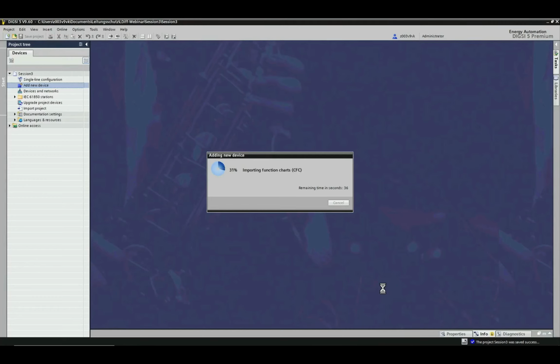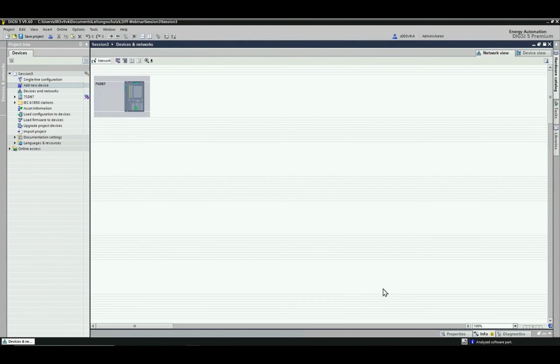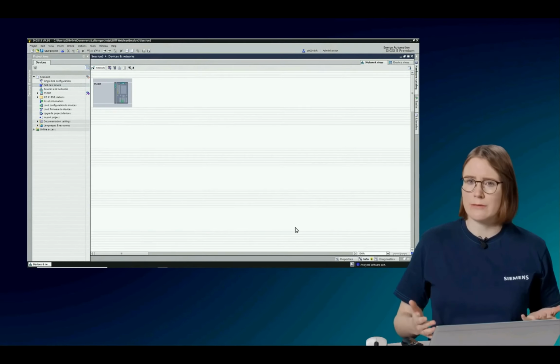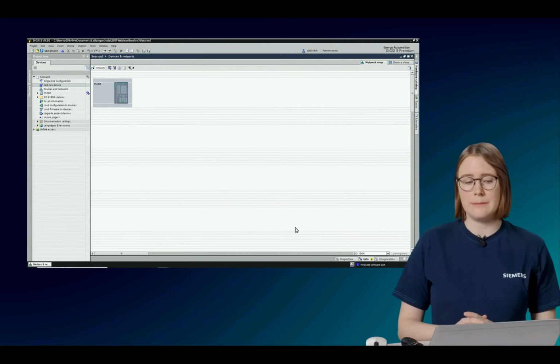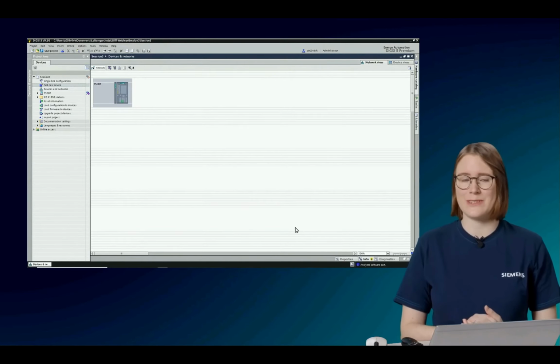So what I like doing at the very beginning of creating a project is to set the correct language and to set the correct setting mode. So do I want to do the settings in setting mode primary or in setting mode secondary? Of course, those two settings can be changed afterwards, but especially when it comes to the language, and for example, you use user-defined signal names, then you switch the language, the names won't be changed in the new language.